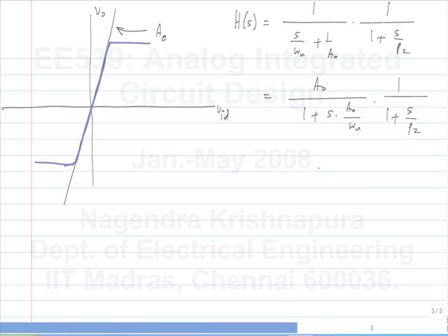So the op-amp has two input pins and an output pin, and also it has upper and lower power supplies. So what will be the saturation voltages? VDD and VSS. In reality, it will be slightly below VDD and slightly above VSS, but we'll approximate it by assuming that it is VDD and VSS. In fact, let me not do that right away.